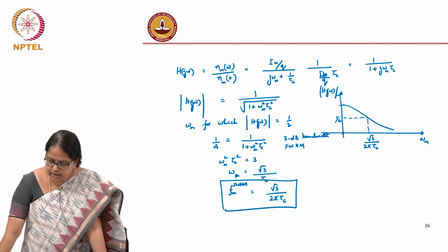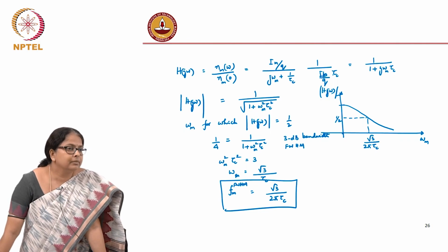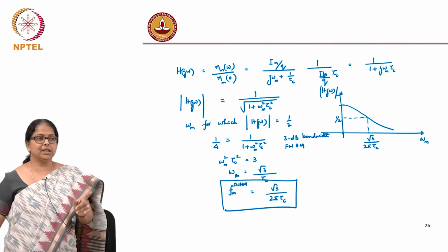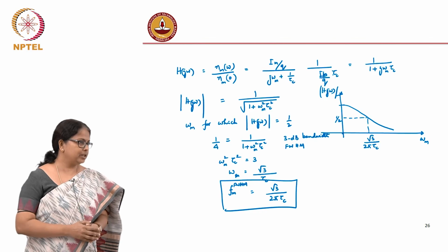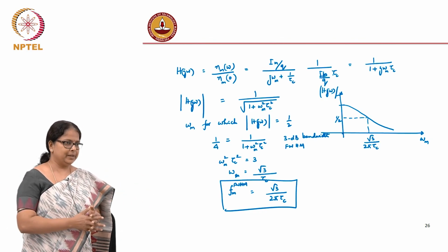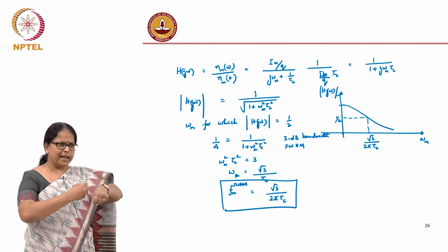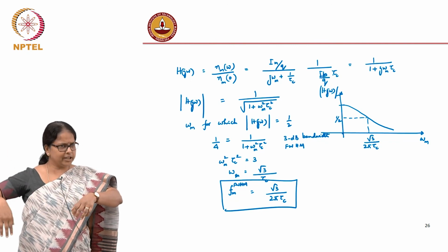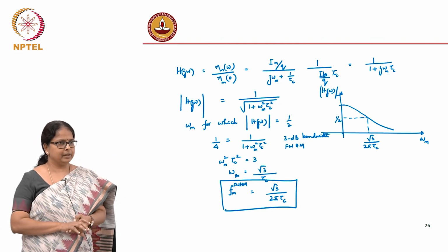The question is, so what finally decides the modulation bandwidth now? It is the recombination time, and it is not just the radiative recombination time, it is the radiative plus the non-radiative recombination time. Larger the time, smaller is your bandwidth. It is like saying that the recombination itself is taking a lot of time. So, my carrier density cannot respond as fast as my input modulation speed, and so the response drops. Alright.